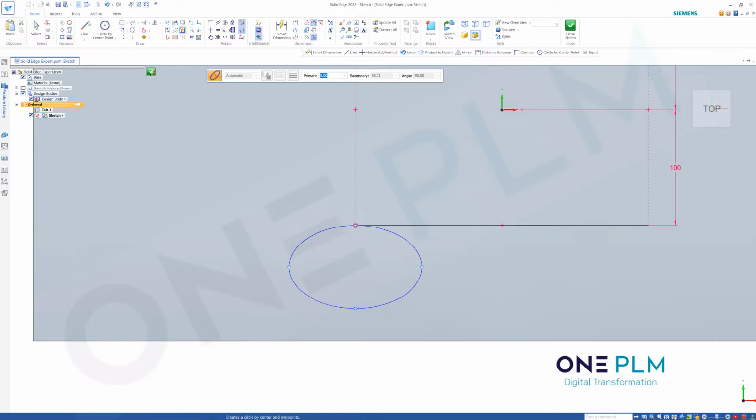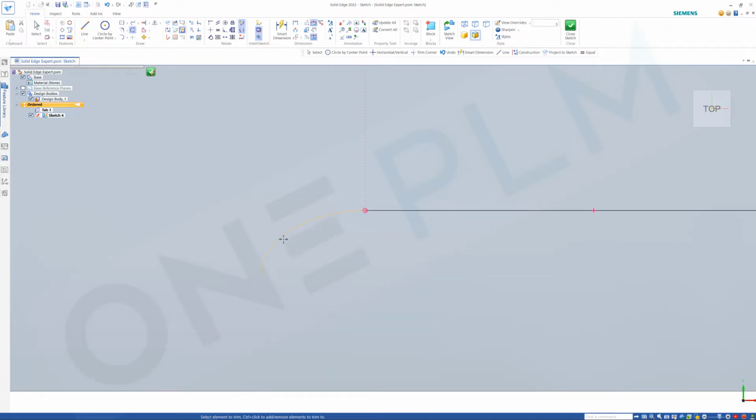So that is the kind of shape that we want on there. I then want to go and trim this lip, so I'm just going to do a line from the quadrant point, silhouette point on the left to the center, and then back up to the top. Use my trim command, trim that, and trim those two, just using the scribe command on there. So if we go back to select and click on this line and click on this little end point, you'll see that that is actually retained, that is actually part. You can see that we've got our silhouette points showing, we've got our center points.